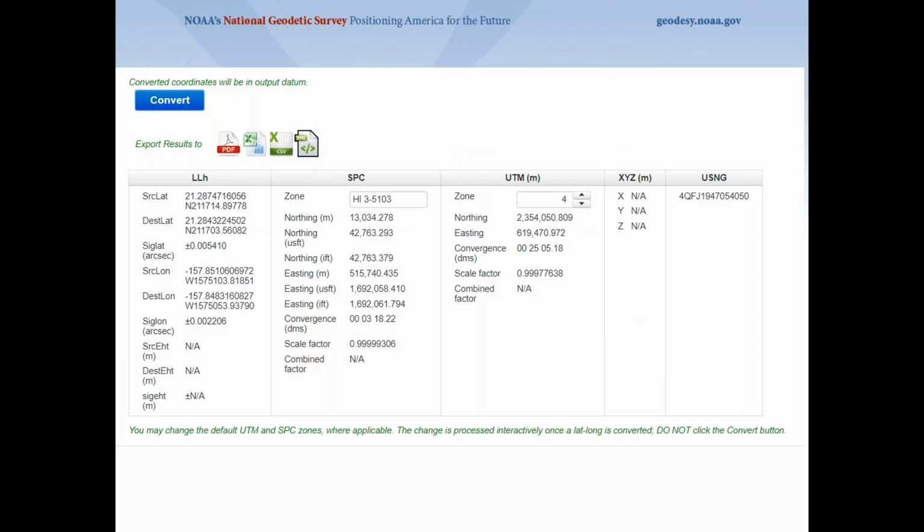And here's what I'm talking about. Here's a conversion that I did before. We have the northing and easting in feet. We have US survey foot and international foot. And you can see that in the northing, the value of the feet is very, very close, 8 hundredths of a foot, but in the easting it's 3.9 meters.